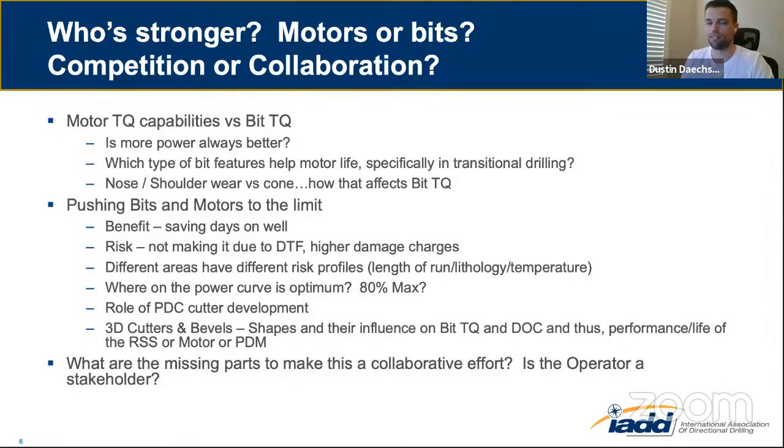If your motors are breaking, I suggest you either work with your vendor to not break them or find a different one, because this is largely a thing of the past. Also, outside maybe the ultra high, the high temperature stuff in Haynesville, et cetera, or if you're doing extremely long runs in South Texas, curved laterals, that's a slightly different prospect. But any of the West Texas Permian stuff, motor failures are gone.